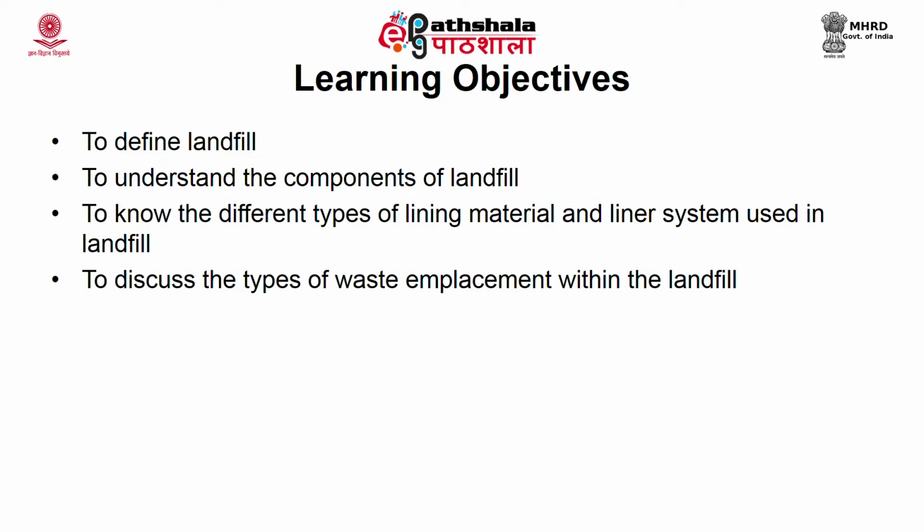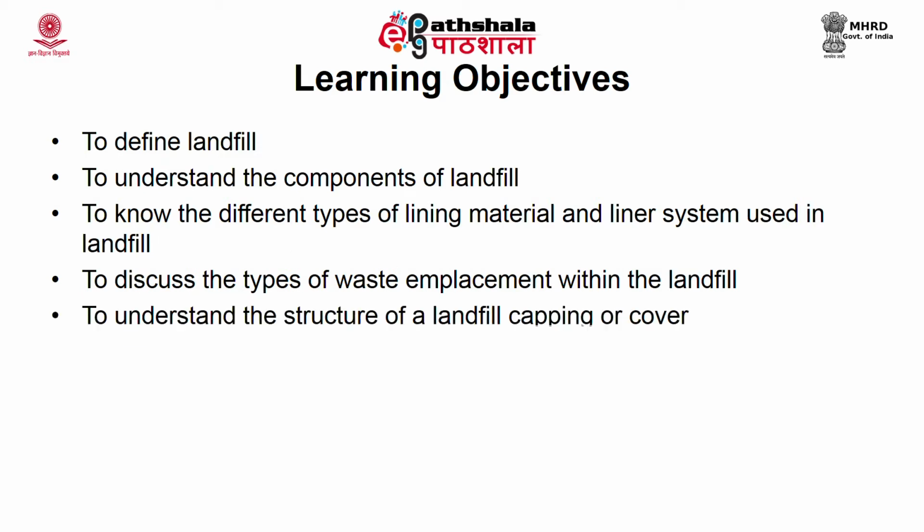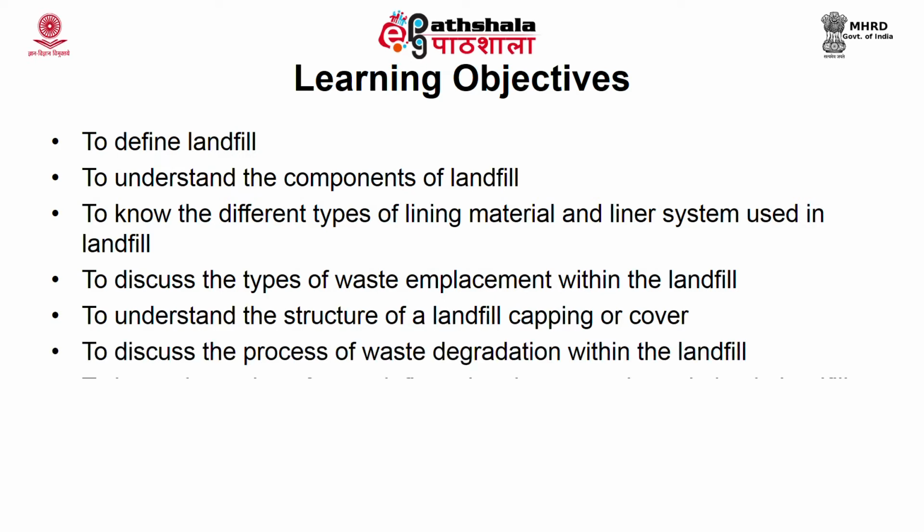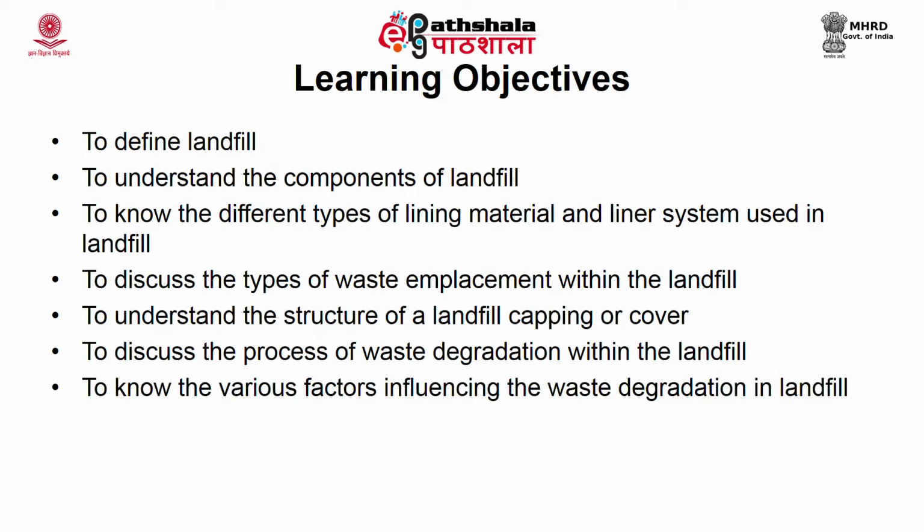We will discuss the types of waste emplacement within the landfill, then understand the structure of the landfill capping or cover material used as the final layer. We will also discuss the various processes of waste degradation within the landfill, and finally, the various factors influencing waste degradation in a landfill.